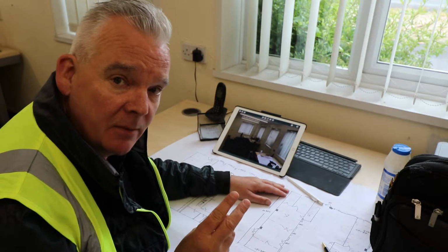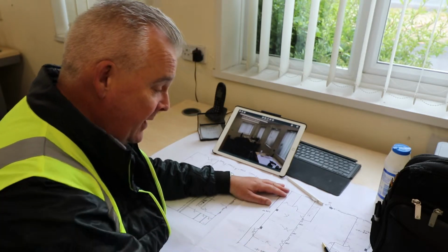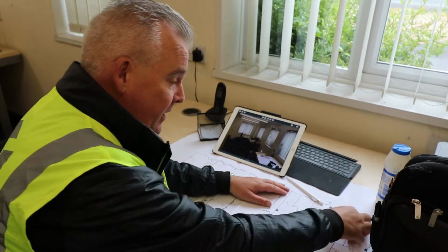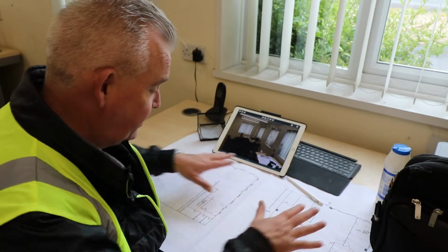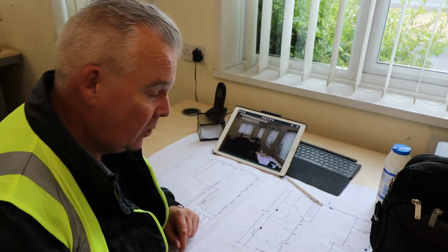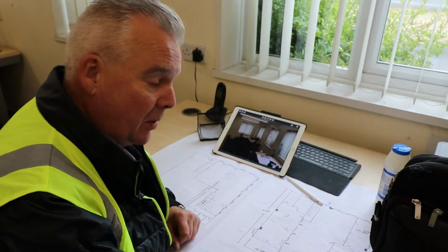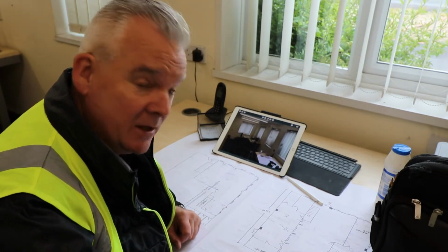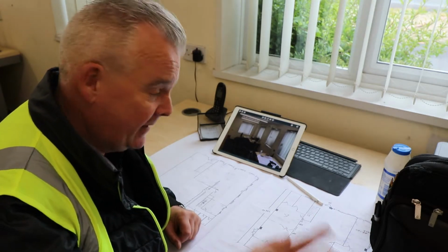That allows a double check to make sure that we have achieved all the correct measurements. If we can work this out on scale, on plan, we've got all the internal measurements, we've got the overall dimensions correct, we've got 2 floors here, then we know that we have got the information. What will happen more often than not is we will get to a point where it doesn't actually work out, we maybe have written down the measurements incorrectly. We've got a chance then to go back and just get it right.